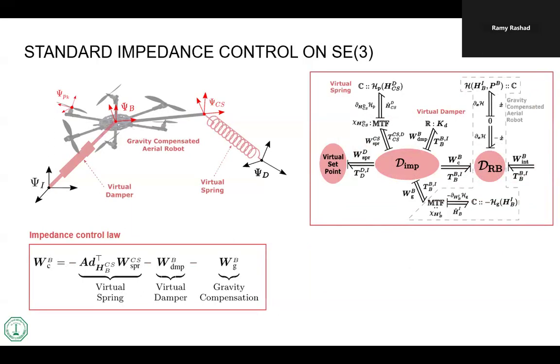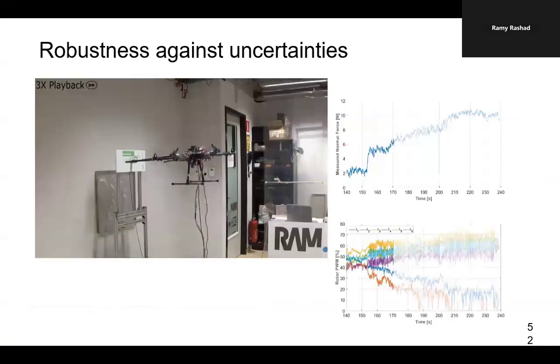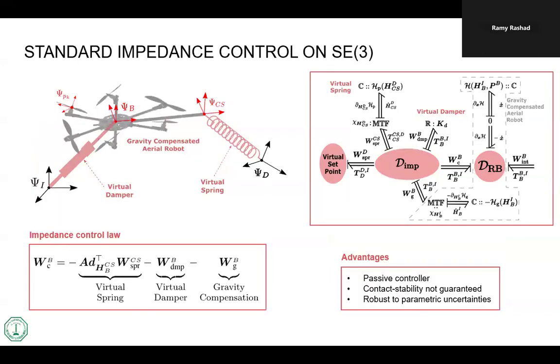So some people say that I'm going to be using Euler angles, desired and actual Euler angles, and then I have a linear spring. So I just have these two springs. This doesn't generalize well, has very bad properties. And when you use it for interaction, you get horrible stuff. Okay? And this is one of the very big results in force control in general, that people that started to use just linear springs like this, they got very bad, very weird results. That should not be the case. And actually, they prove that you get better results when you do everything geometrically consistent. Okay, so I'll give you some reading material if you want on that part.